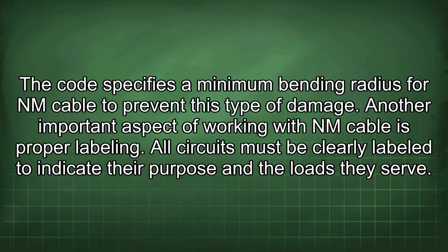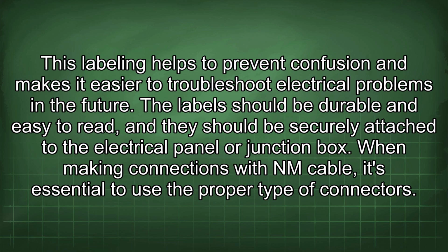All circuits must be clearly labeled to indicate their purpose and the loads they serve. This labeling helps to prevent confusion and makes it easier to troubleshoot electrical problems in the future. The labels should be durable and easy to read, and they should be securely attached to the electrical panel or junction box.